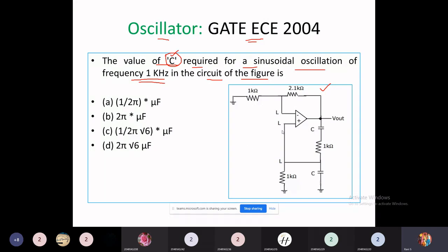The given circuit, if you consider, is it an inverting amplifier or non-inverting amplifier? Because the inverting terminal is provided with negative feedback and the other end is connected to ground potential. And the actual input signal appears only at the non-inverting input. When we compare with the four oscillators we have discussed, like Wien bridge oscillator, phase shift oscillator, and other LC oscillators, normally the phase shift oscillator and two LC oscillators operate in inverting mode. Inverting mode amplifier introduces 180-degree phase shift.